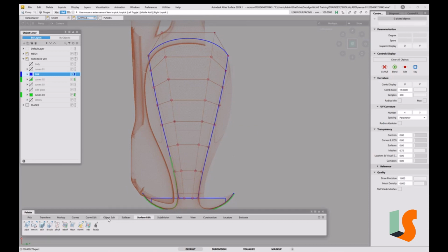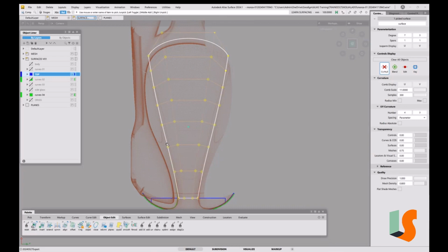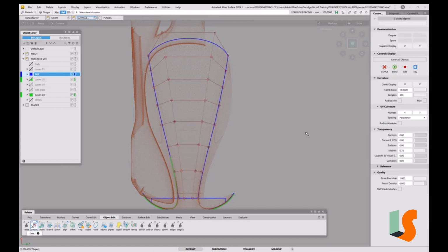So what detach does is it'll keep 100% the original surface. So I'm deliberately going to create a copy of that surface just so I can prove that. So if I say, actually in detach, does it have an original? Keep originals, that's what we want. Excellent. So I'm going to do that.